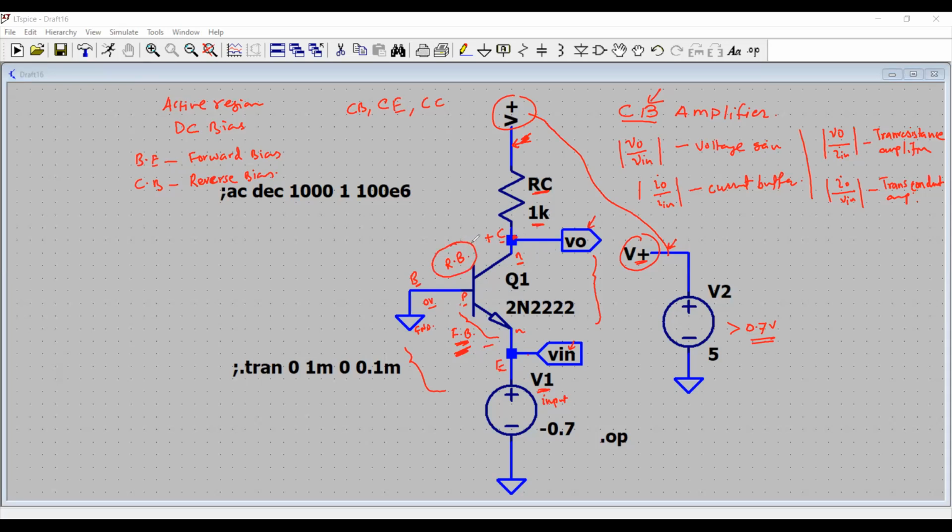To do that, the possibility is that you simulate the circuit to understand its DC operating point. For that, I am using the SPICE circuit simulator, and I will run the .op analysis to obtain various voltages and currents in the circuit.